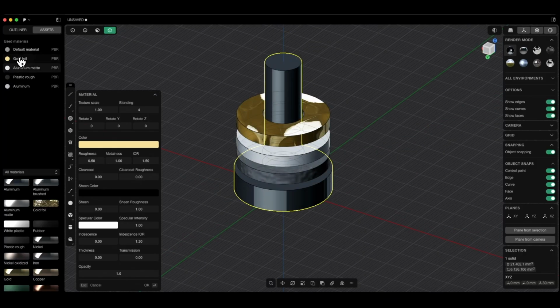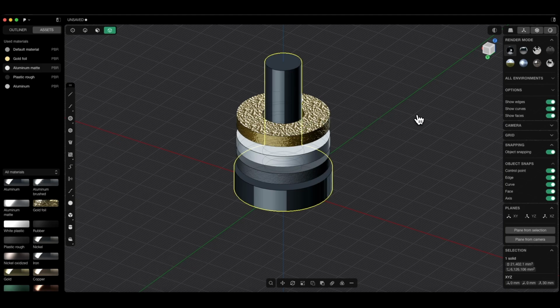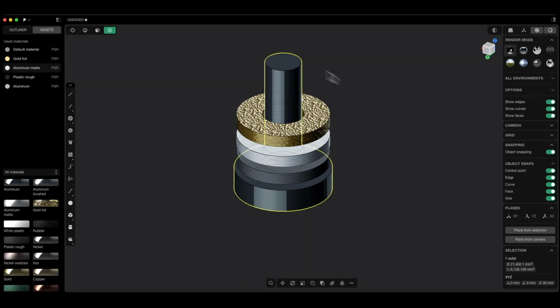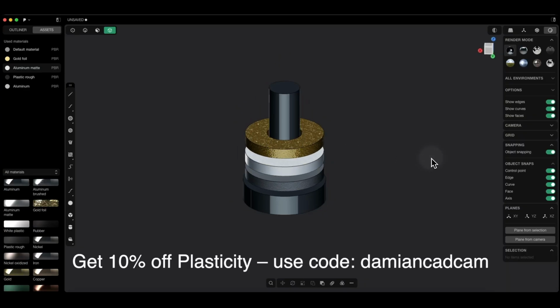For each material, we can activate it and adjust its parameters, including scale, which can help fine-tune the appearance, especially for small elements. In some materials, the change is clearly visible, in others, less so. If you want to make a simple visualization, you can hide the grid and coordinate system and also turn off X-ray mode so hidden edges are not visible. This way you have a clean, simple presentation of your model.